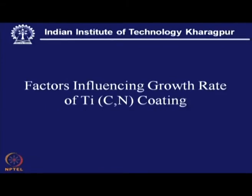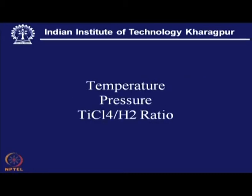Now, factors influencing the growth rate of TiCN coating. Naturally one would be interested to know what are those factors, because there are certain operational parameters. Once the CVD is established, we have to control those operational parameters, and those parameters can be summarized as follows. Number 1, immediate attention is temperature, then comes the process pressure, and finally it is TiCl4 to hydrogen ratio.